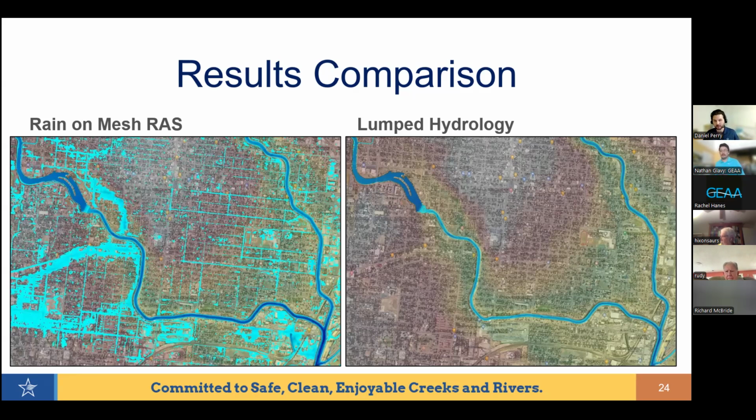So you can widen the channel, but you also keep that low-flow channel in the middle there, and you try to really make sure you're keeping that area as natural as possible with the correct natural vegetation of the area. But yeah, a lot of the time, especially when you're just considering flooding, it does end up reducing the vegetation and sometimes the riparian area.